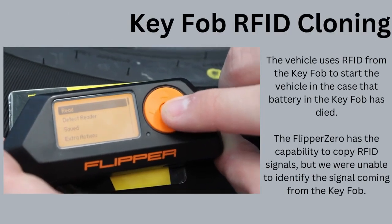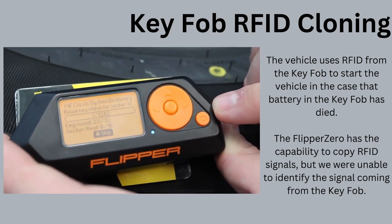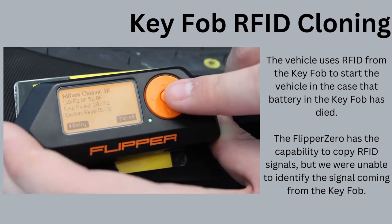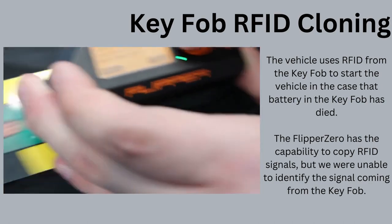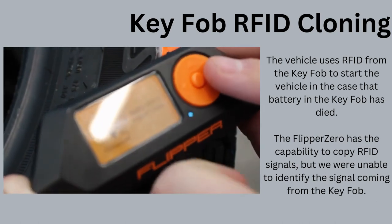Modern key fobs for vehicles equipped with keyless entry include the ability to start the vehicle even if the fob battery has been depleted. The operation of this method involves setting the key in the center console so that an RFID signal can be read from the fob so that the car can be started.